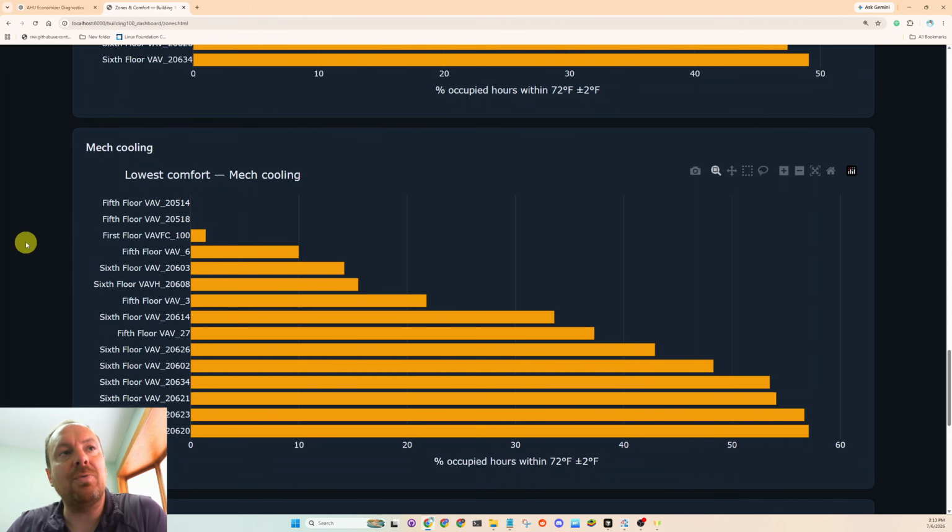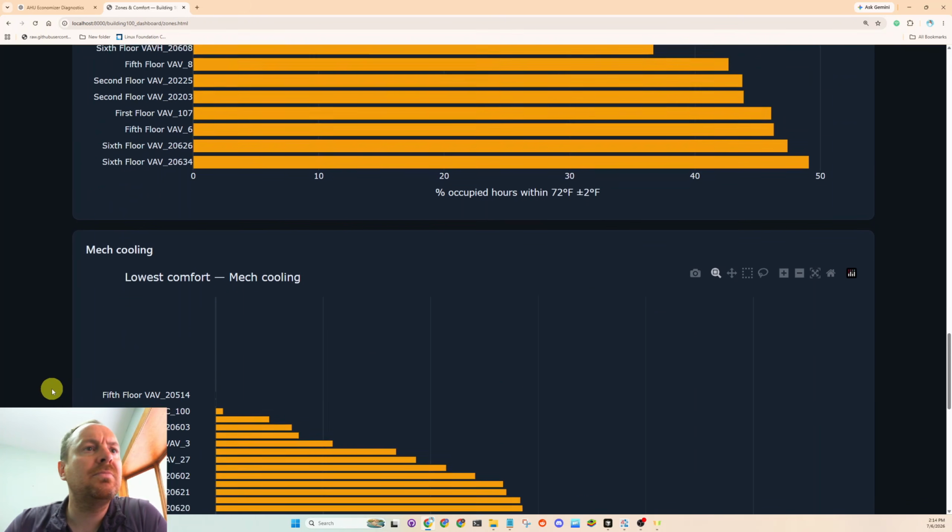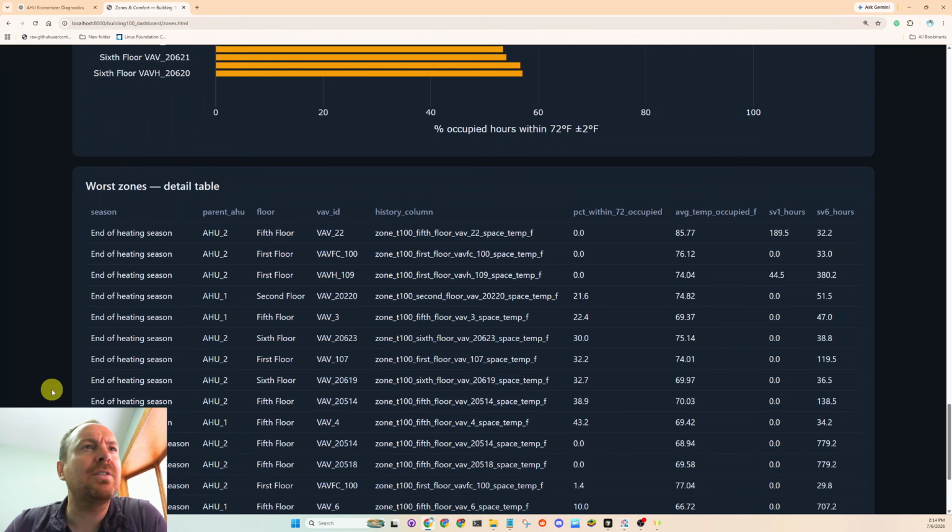So this could be something where, if you were in a retro-commissioning project, you don't have to fix, you have to visually test a percentage of the building. With some data like this, you could zero in on, let's go physically look at these boxes and stroke all the dampers, make sure the reheat valves go back and forth, like visually put eyes on it. So we do like those.